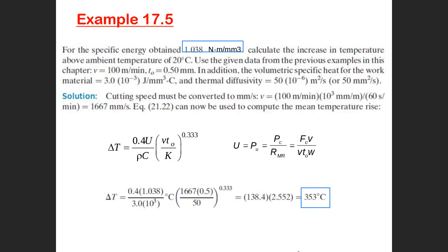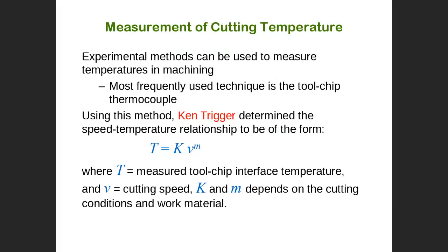When you get the temperature in the cutting zone, then you can realize whether this temperature is okay or not. Did we reach the critical temperature in the cutting zone? You can know whether it is okay or not. If not, then it should be fine and we can use dry cutting. But if the temperature really exceeds the critical limit, in this case cutting fluid should probably be considered. This is the importance of using this equation.